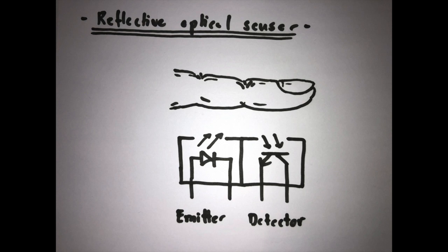How does the sensor sense our pulse? Infrared light is emitted and hits the surface of our finger. Inside the finger, it lands on deoxygenated hemoglobin, which then scatters off and out of the finger and into a detector. The pulse is defined by the variation of blood volume in the skin due to the pressure pulse.